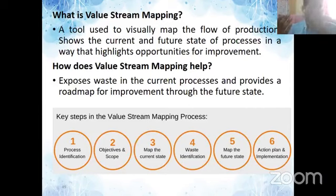So it is your flow diagram of your product right from start to finish. At each step, we determine the different inputs and outputs, and based upon that, we find out the loopholes in the system or the different wastes that happen while processing a product. These are the key steps in value stream mapping: process identification, objective and scope, map the current state, waste identification, map the future state, and action plan and implementation.